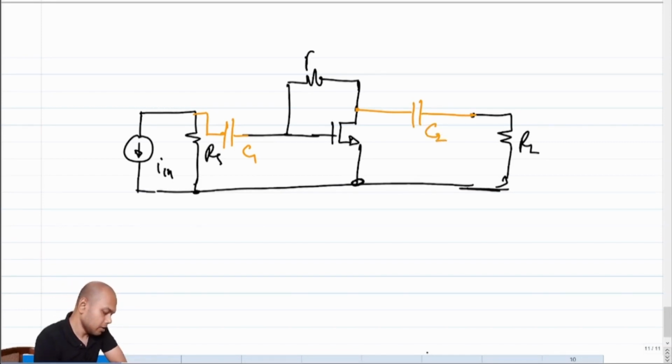This is R. But you might be now screaming at me saying that how have I biased the transistor M1? This is clearly not biased, because what is its gate to source voltage? What is the current flowing through it? Clearly nothing, right? The gate to source voltage is not applied, it's zero in this case, right? So what should I do? I can simply put a current source, right? We can put a current source bias. Where do we want to put it? In this case, since I already have a connection between the drain and the gate, the connection between drain and the gate is already established.